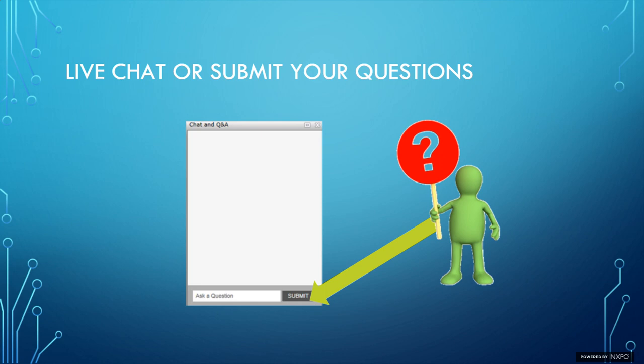Another effect, we just talked about the oil. The hotter the temperature, the lower the lifetime of the lubricant, if that has an impact on the operating temperature of the compressor. So ambient temperature is definitely a factor, and for refrigerated dryers and aftercoolers, that will also produce higher compressed air temperatures, which then increases stress on the cleaner treatments. This needs to be dealt with in the design phase, as Neil pointed out, and that's where compressed air experts can help you to make the right choice.